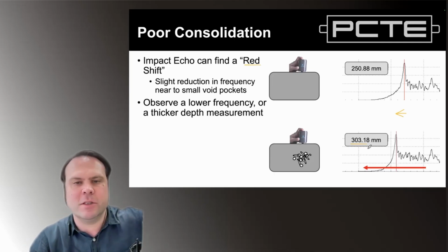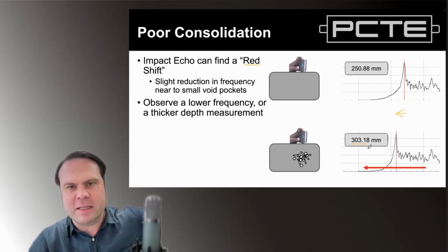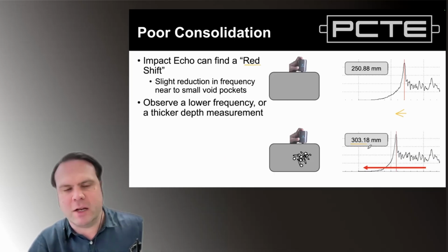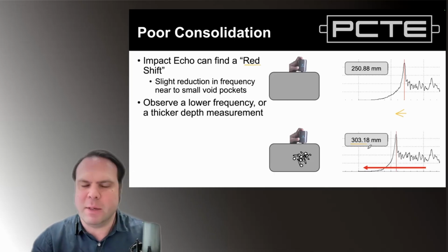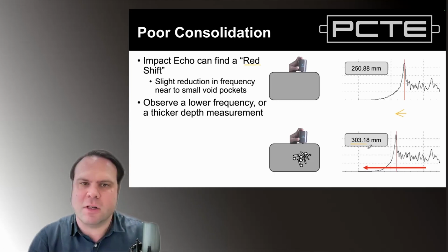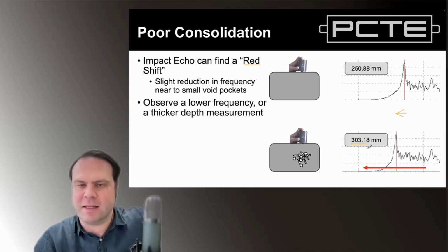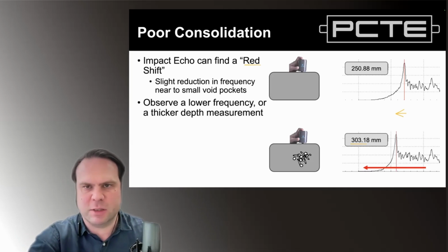Yes, you needed a 250 millimeter thick slab. We did a test and we've got some honeycombing over here. It's the region that I have labeled as 300 millimeters. It's hard to explain, but if you instead say we have a 7,000 hertz frequency, and in this region a 5,000 hertz frequency, that's our defect, that's a little bit more easy to explain.